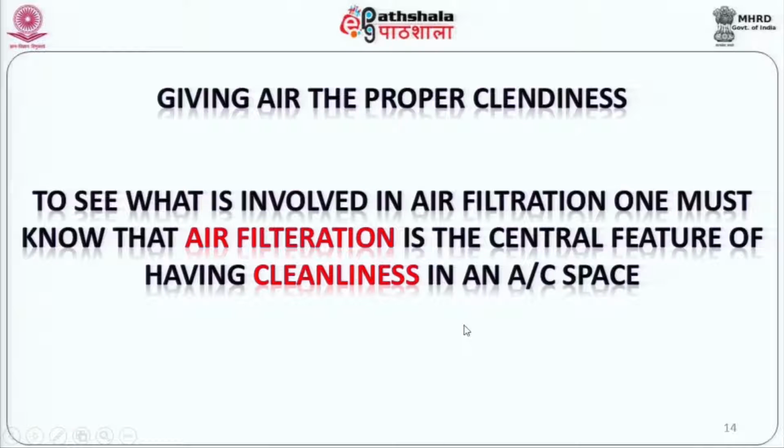Why does one need cleanliness in air? It is basically to effect proper health and hygiene. A hospital needs clean air so that it can control the invasion of bacteria and virus. Bacteria and virus, as one knows, are limbless creatures. They travel only on dust. So in other words, infection is something which moves on dust, and since you cannot catch a bacteria or a virus, you catch the dust, you have controlled your bacteria and virus invasion.